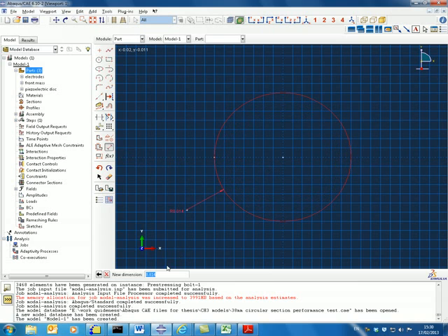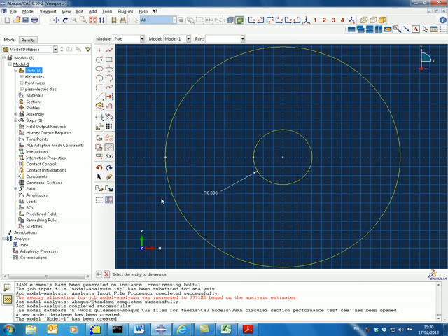The inner diameter of the back mass is 12 millimeter, which is smaller than the piezoelectric material, and when we assemble the shape we will see why that is necessary. So the radius will be 6, and the outer will be the same as the piezoelectric disc, which is 19 millimeter radius.